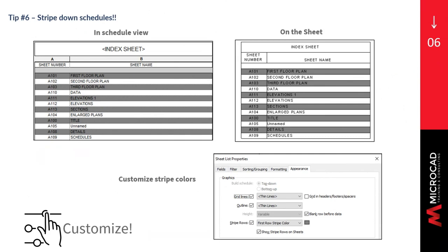As well, you can define stripe colors for the schedules, which is going to be more customizable for all those users that have really long schedules or want to highlight elements within your views or schedules. Specifically, I would say for either plumbing fixtures or lighting fixtures. And if you have a pretty extended schedule, you want to take advantage of this feature and apply it to your drawings.